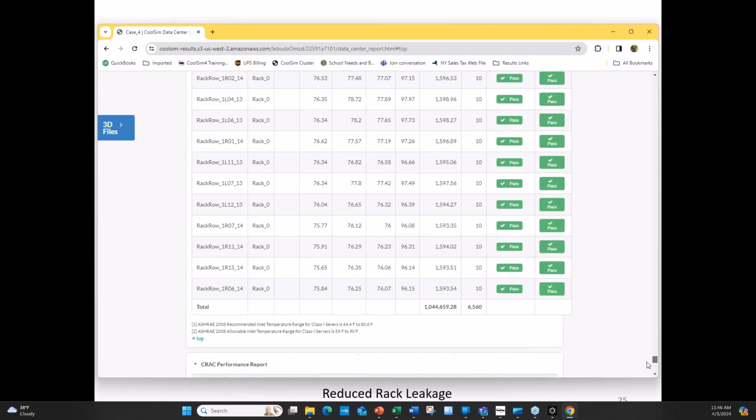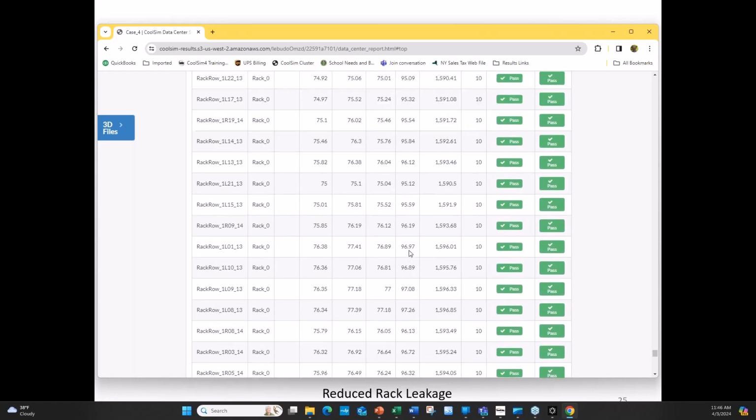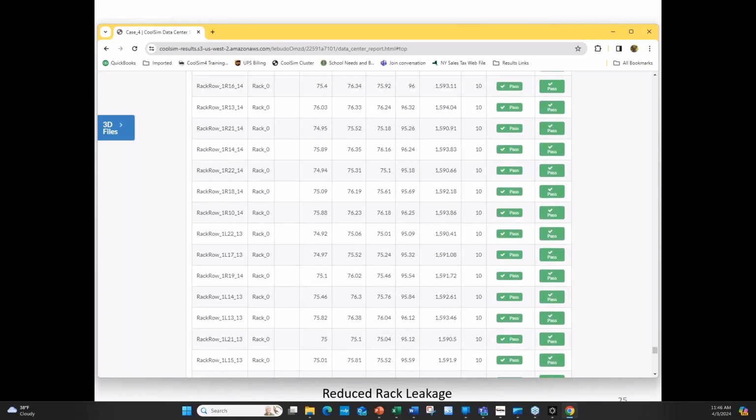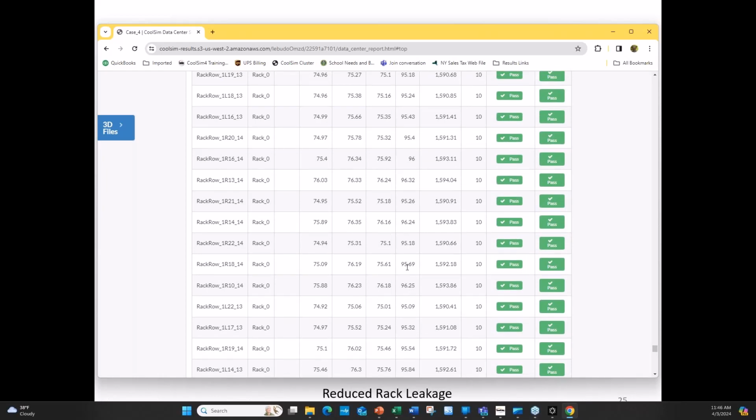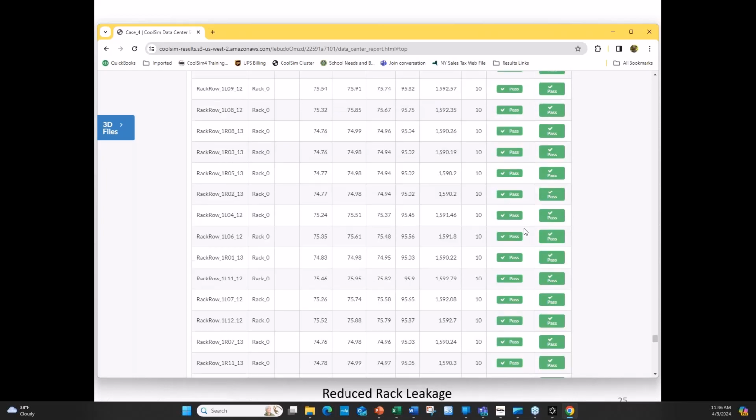So we get down and, yeah, we don't actually calculate averages. I should do that. But you know, the delta T's, here's the return 96. So, you know, 20. It's not quite 25, but the boundary condition was set, and then you numerically try to achieve it. So you'll see it be higher in some cases. Yeah. And you see it's all passing.